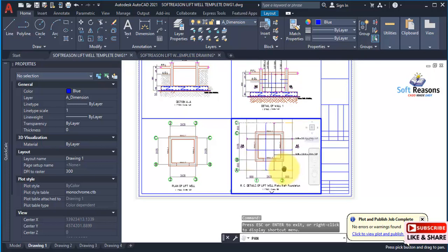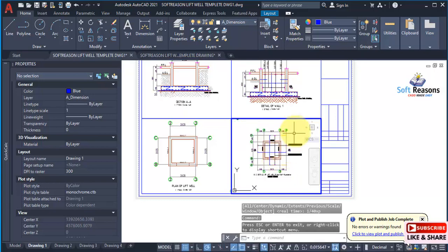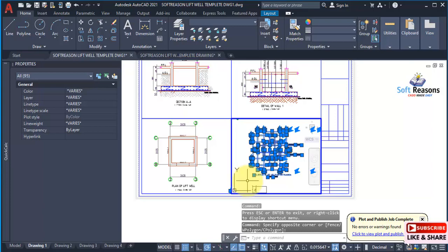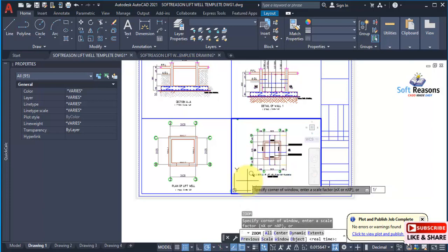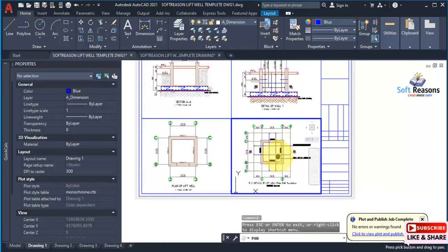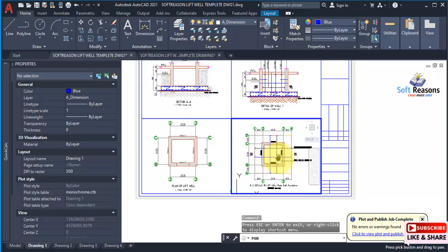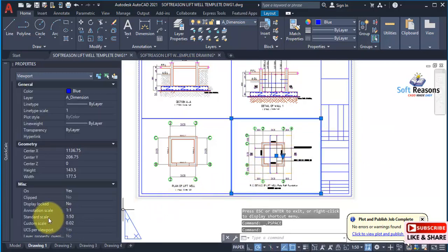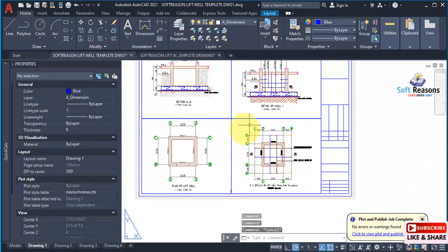All right, so this is bigger. The scale we used here was 1:50, so do that again. Z, enter, 1/50 XP and enter. So use the pan option to pan it just like this. This is okay. Escape, double click outside to deactivate that, select this window, come to Display Locked. It is No, say Yes to that. So now the viewport is locked successfully just like this.